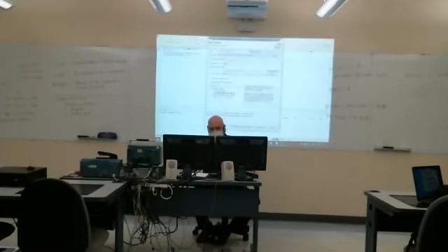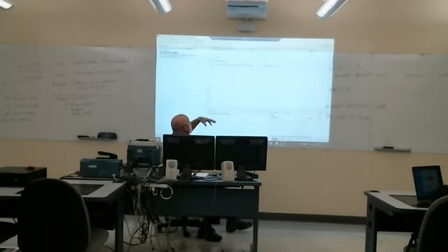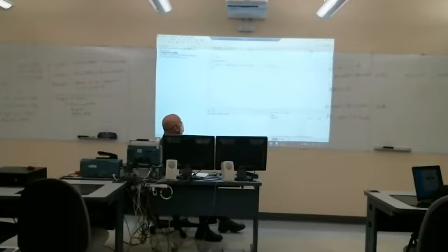And then this is actually going to be stored in your workspace. It'll create this new directory. And it shows you here, if you've got this use default location checked, mine's on my F drive, AR63, workspace version 10 of the Code Composer Studio hello 2, and then finish. And then it will actually create a project. Looks like I can't resize it with my mouse. Can you see that? Kind of an empty program at this point.